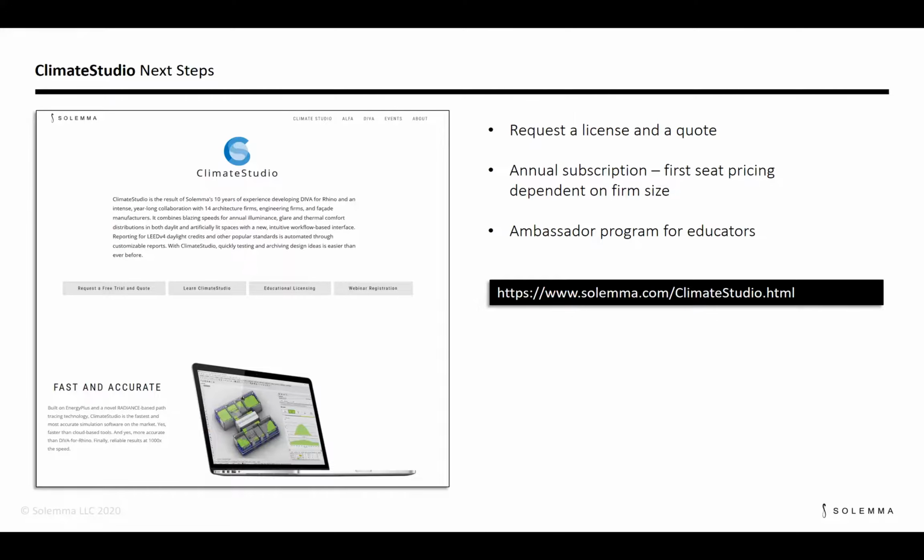And actually there was a question a couple of times about the simulation parameter settings for Radiance that we are using. The simulations that you saw were with an ambient bounce of 6 and an ambient accuracy of 0. The 0 we are setting due to the path tracing approach that we are following. You can change this when you go to the settings under the different workflows.